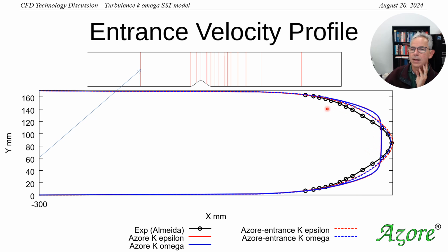And so if you look right up in here, the solid line is our previous prediction, where we didn't really capture the boundary layer development. Now if we increase our distance, we have given our domain the chance to actually predict that fully developed flow. And the solution looks much closer to the data. So simply changing our boundary condition has significantly improved our prediction at this location.